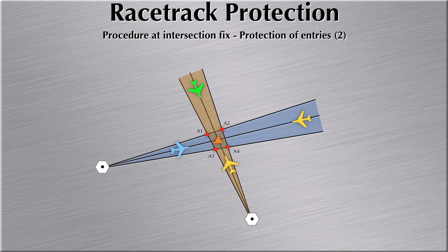That means you have one fix created with the blue radial as the tracking and the amber radial as the intersecting, and one doing the opposite. If you want, you could be pragmatic here and generally construct the intersecting fix area based on two tracking tolerances. It's going to be a little bit more conservative than necessary, but it saves you some hassle.